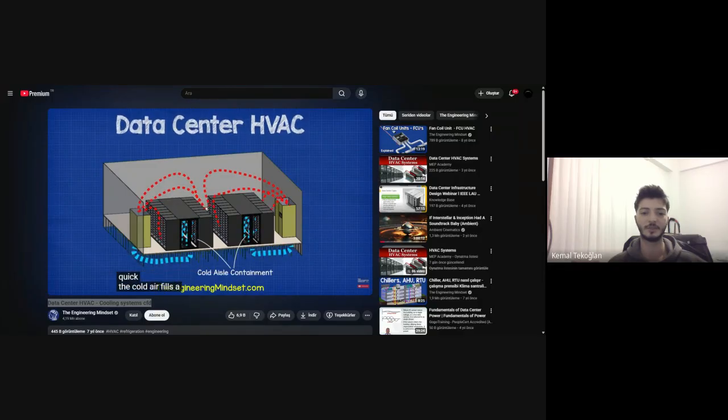The cold air fills the cold aisle, and then the hot discharge fills the rest of the room, with the CRAC units pulling this in for reconditioning. However, it does also mean that any equipment located outside the cold zone will only receive hot air.